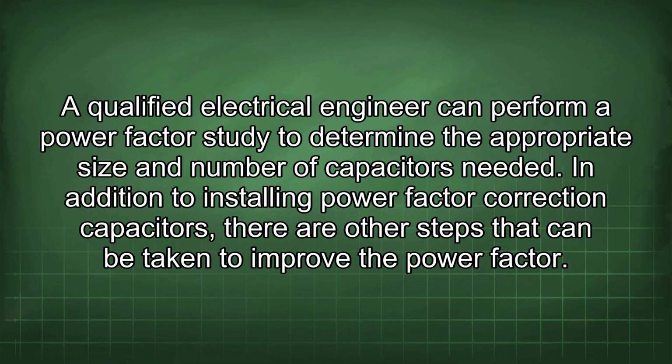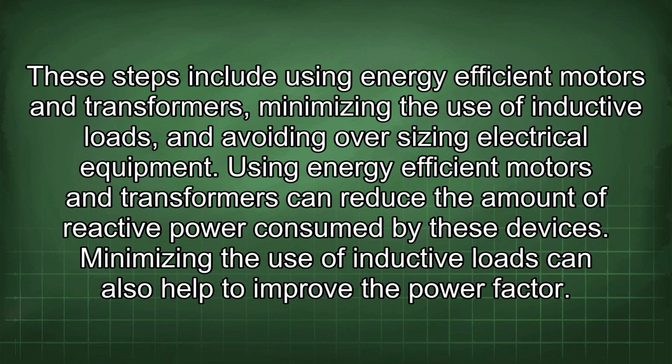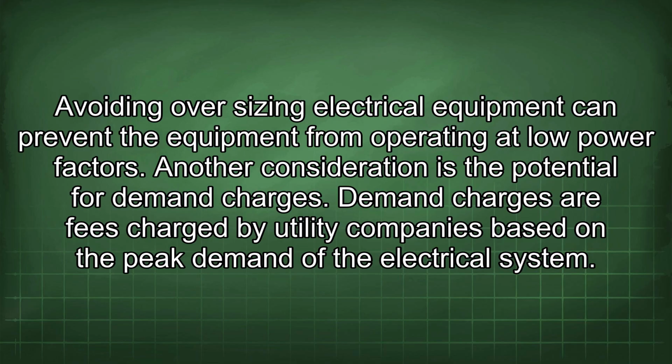In addition to installing power factor correction capacitors, there are other steps that can be taken to improve the power factor. These steps include using energy-efficient motors and transformers, minimizing the use of inductive loads, and avoiding oversizing electrical equipment. Using energy-efficient motors and transformers can reduce the amount of reactive power consumed by these devices. Minimizing the use of inductive loads can also help to improve the power factor. Avoiding oversizing electrical equipment can prevent the equipment from operating at low power factors.